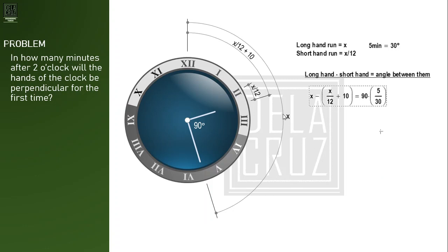So let me just input it here since I am using the MathCAD software. Yung syntax sa MathCAD natin, find, I have here the given initial value guess of x, let's say 1. Any value dyan, no? So we have here x, find the value of x.